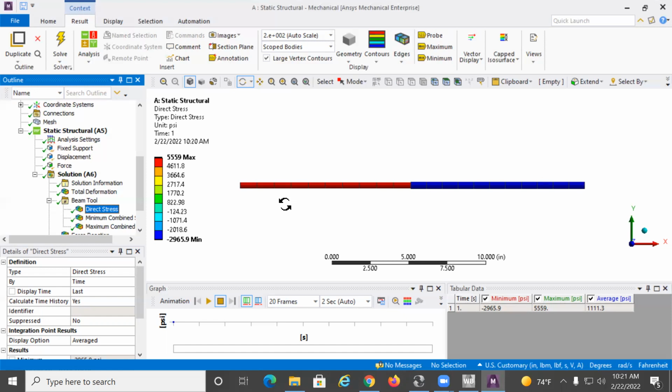So you're going to start noticing that the homework assignments are going to ask you to redo some of the problems we did earlier in the class using ANSYS Workbench. Like homework 5 is exactly the same as homework 4 that you did by hand, but you're going to work it using ANSYS Workbench and using beam elements. So you're just going to be creating these lines, material, meshing it, apply the loads and constraints, and do exactly the same like we did for this example.